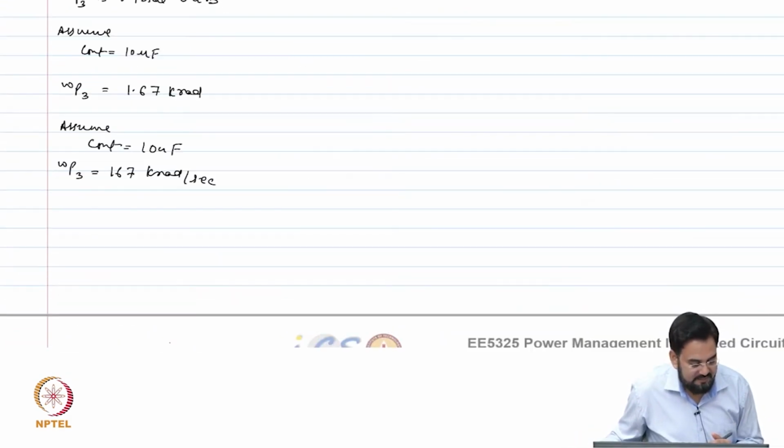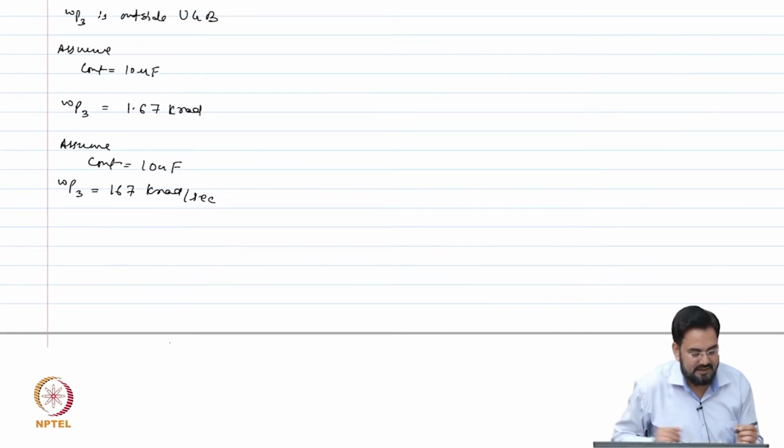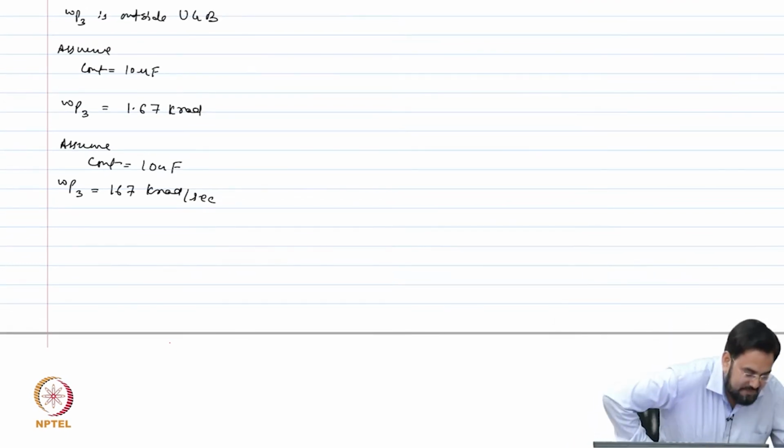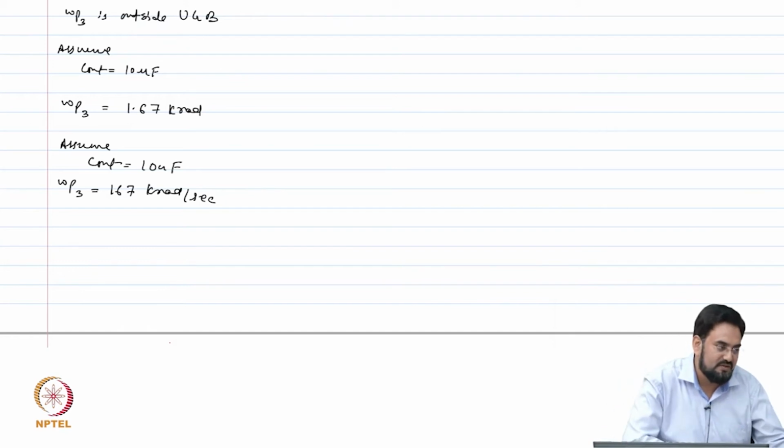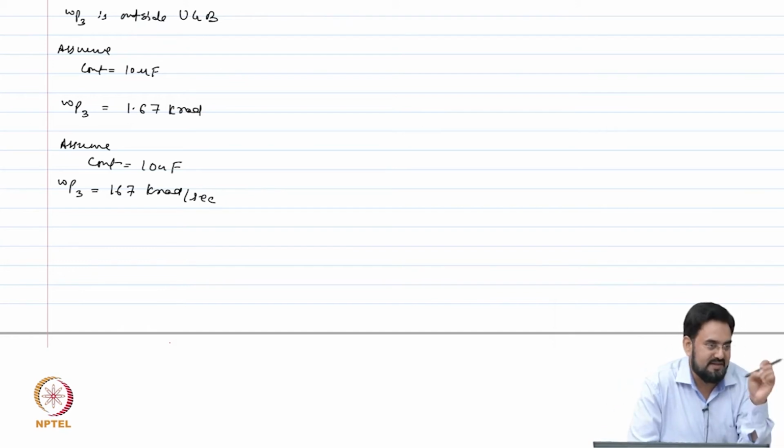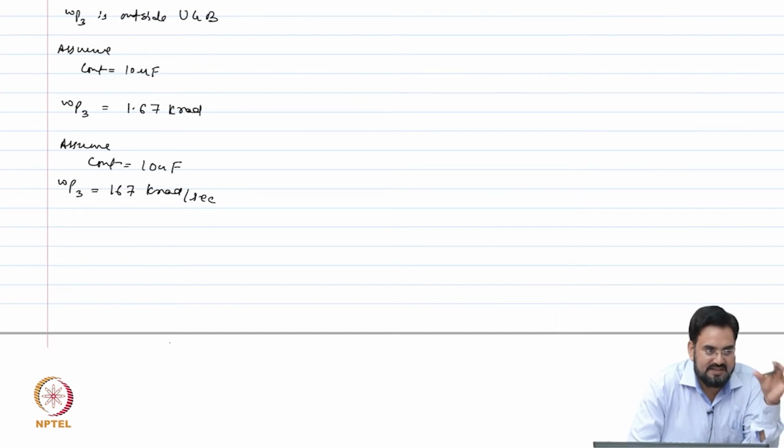Most of the time, when we are designing a capless LDO, or capacitorless LDO, where on the output we do not intentionally put any cap, there are only parasitic caps of the order of picofarad. In that case, you have to design for, or compensate for, the lightest load, which is of the order of microamps.